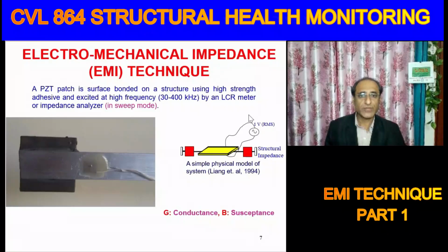So what we do, we excite the structure by exciting our piezo patch into vibrations, and for that purpose we are applying an external excitation, a harmonic signal, which is applied in a sweep mode. Sweep mode means that we are changing the frequency of the impressed signal with time. Alright.